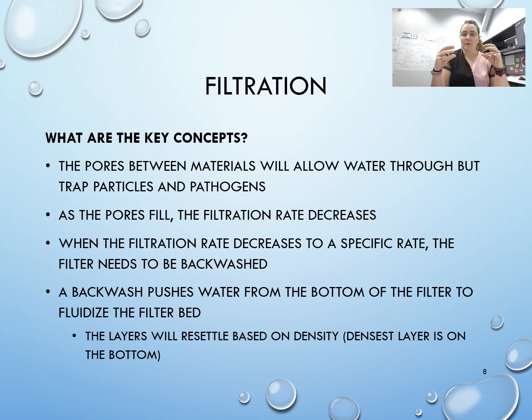One thing that's important about what you put in your filter media is that if it's going to settle, you want the densest, or the heaviest, thing to be on the bottom. Gravel is heavier than sand in water, and so it will settle out faster. So we naturally let our filters settle back down via gravity. Same principles as settling in a sedimentation tank. We put the densest material on the bottom, and so they're naturally going to settle out.